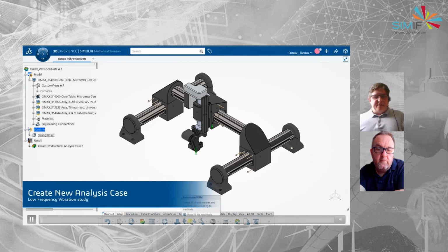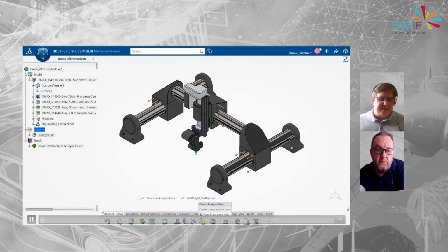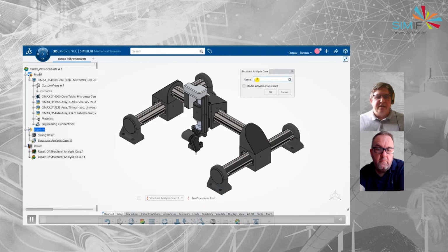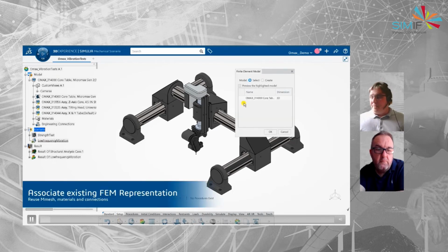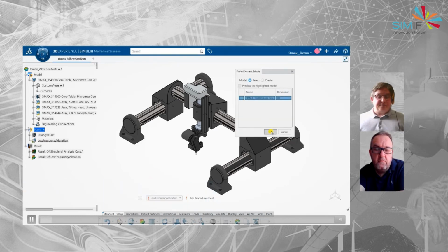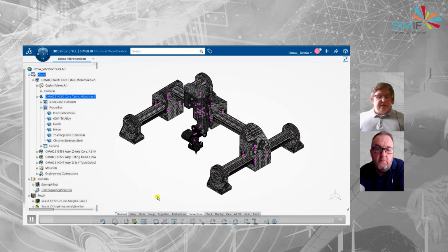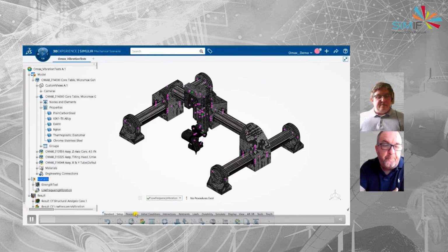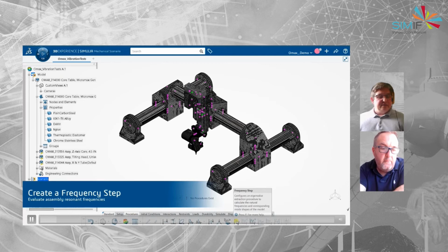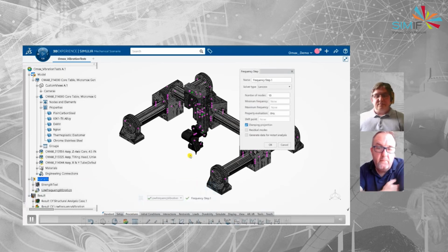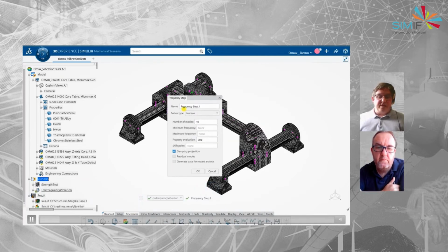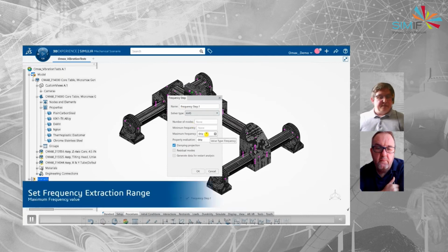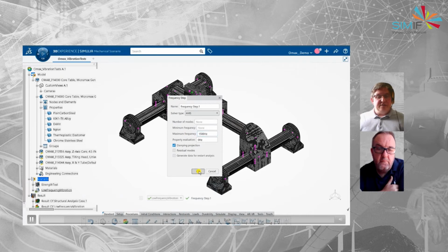So a bit of a lengthy video, this one, but now we need to create those analysis cases. The first one we're going to do is the low frequency. Oh no, sorry. We create the frequency step with a maximum frequency of 1500 hertz.